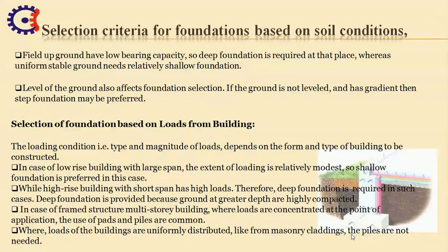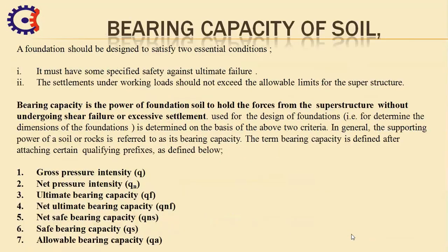Second, concrete piles carrying in situ concrete slab, raft foundation. In case 3, where the trees are cut down shortly before the foundation construction begins, in that case we are going for reinforced concrete pile, strip foundation, raft foundation. If there is soft clay, in this category including soft clay, soft silty clay, soft sandy clay and etc., in that case we are going for foundations like wide strip footing, raft foundation, pile foundation.